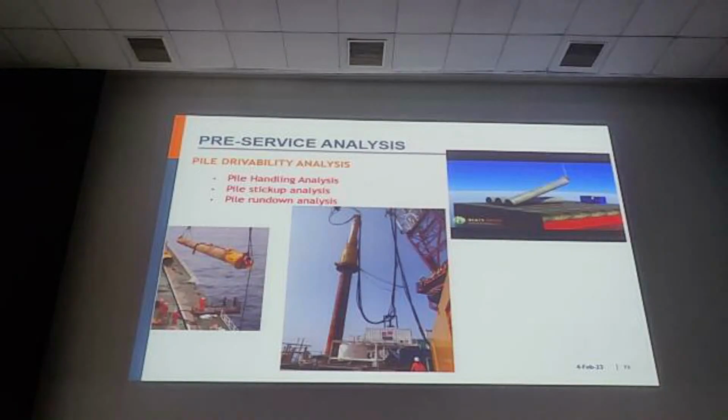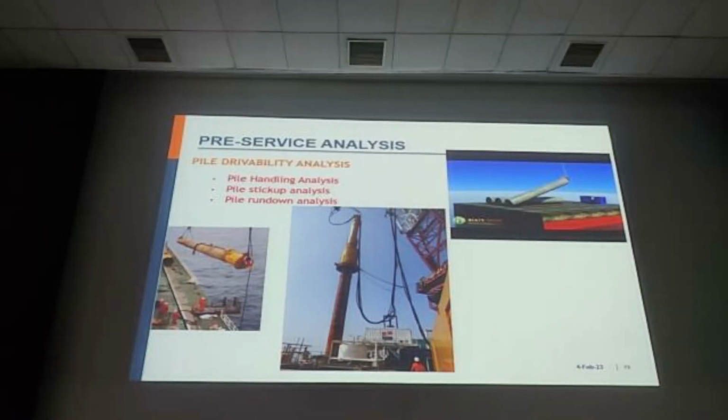There is also the possibility of pile run down, and run down in the sense that if somewhere in between the soil is weak, while driving itself the pile can go in. Then you can pull the pile.